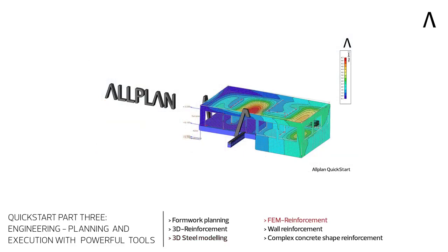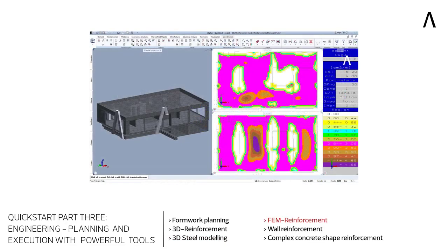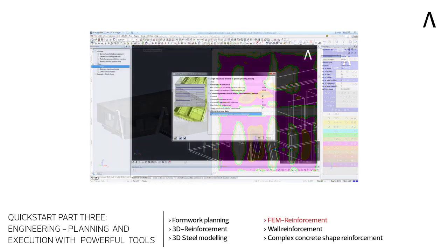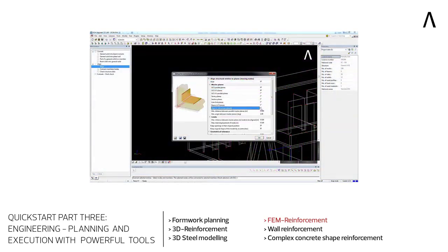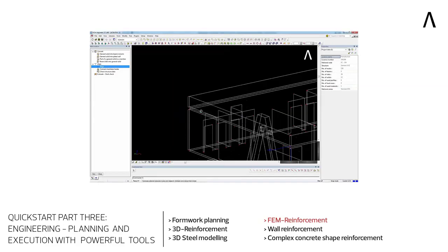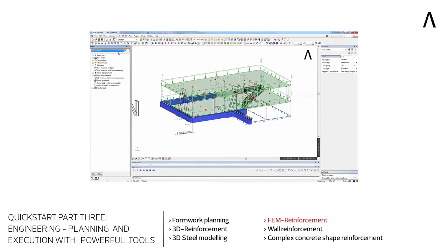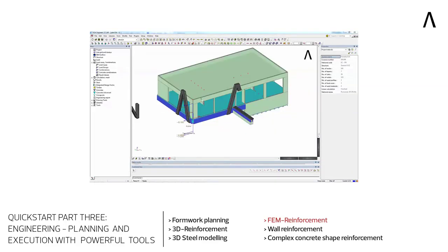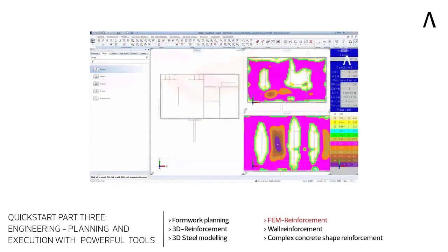The building model created in ALLPLAN can be converted into an analysis model in SIA Engineer via IFC. The design in SIA is based on Eurocode and the results are exported to ALLPLAN as ISO lines of the required reinforcement. The final reinforcement in ALLPLAN is based on the theoretically required reinforcement. The system can also provide an automatic solution containing all details with corresponding bending lists.